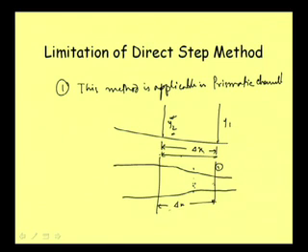So we have computed the depth from 1 to 2, but as we did not know the delta x beforehand, we have ended up computing between two sections between which we cannot at all consider the channel to be prismatic. This is a non-prismatic type, and so the calculation we are doing will definitely be erroneous. So, this is one limitation.